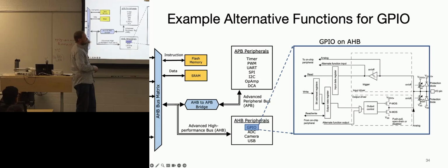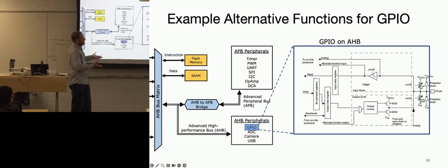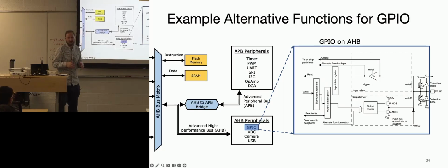And you're going to do it through loads and stores from your core, and then every piece of functionality is available to you. You just have to read through the data sheet and be like, okay, that's the register I need to use to make this function happen. So a lot of what happens is, we try and teach you enough to read the data sheet, and then we just let you loose. You want to figure out how to make your I2C, or that communication bus, go high. Which register? I don't know. Look in the data sheet. As long as you know it's there.